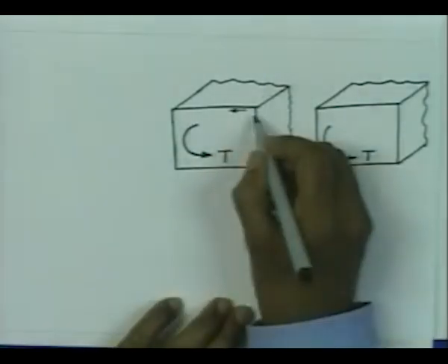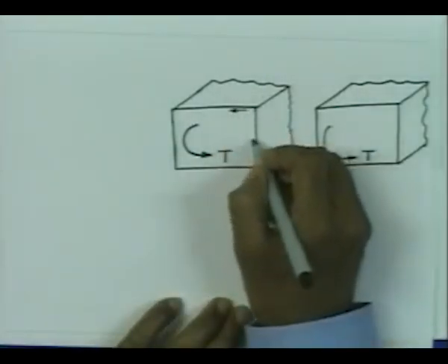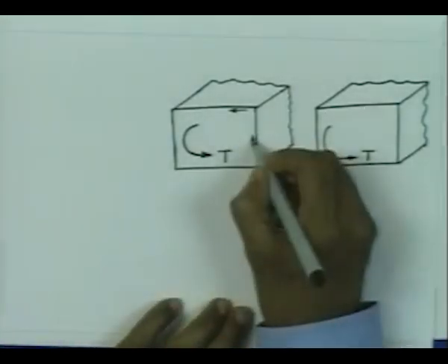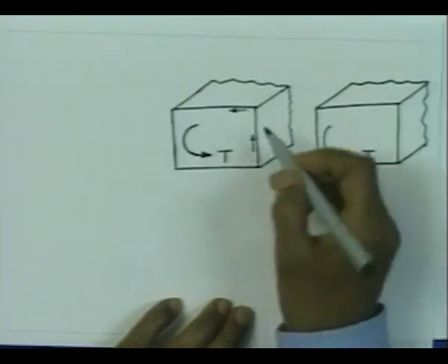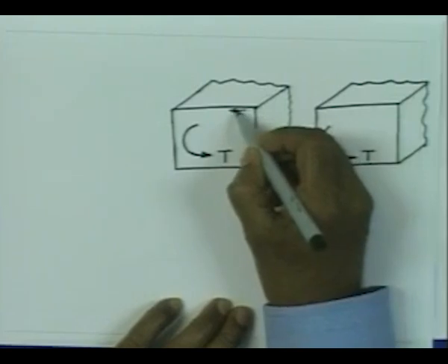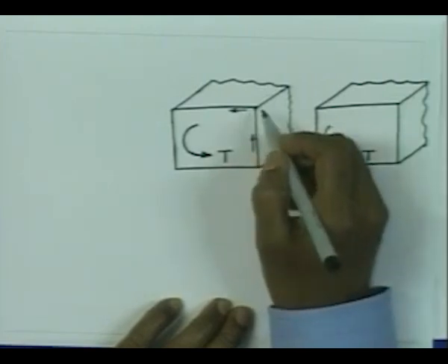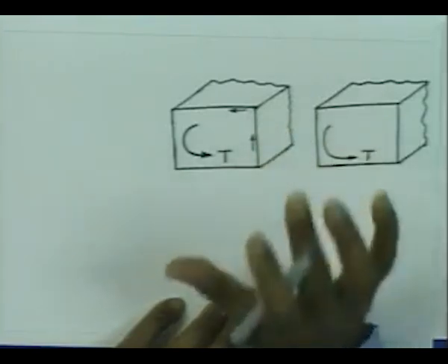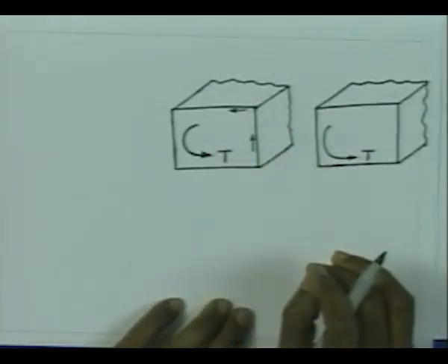close to this boundary, and if we consider this boundary, stress is going to be acting like this close to this boundary. Now, at the corner, which is a common point, there is therefore a possibility of stress acting in this direction and also in this direction. It is a single point and it cannot have two directions of shear stress acting, and therefore, from the uniqueness of the stress, both the stresses have got to be 0. That is from the consideration of the uniqueness of the stress.